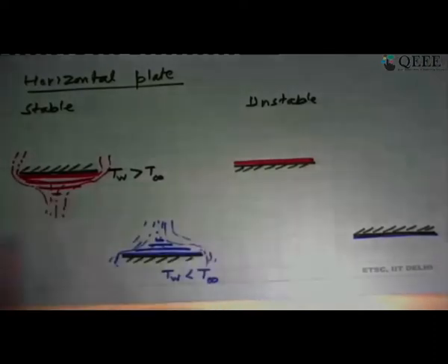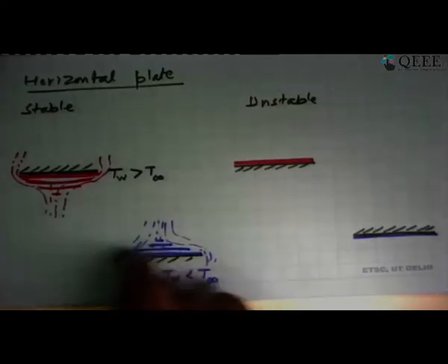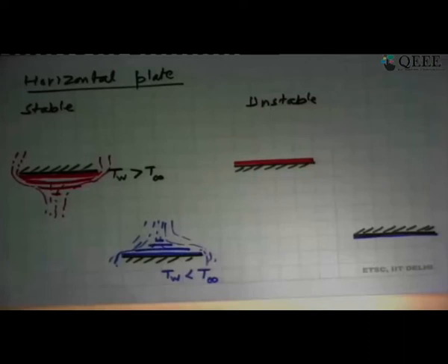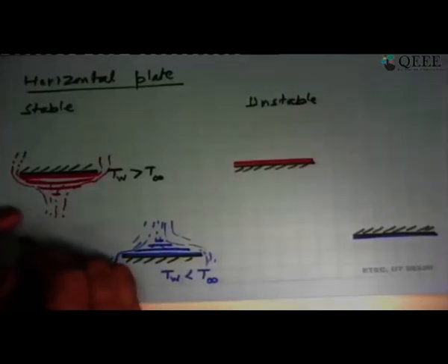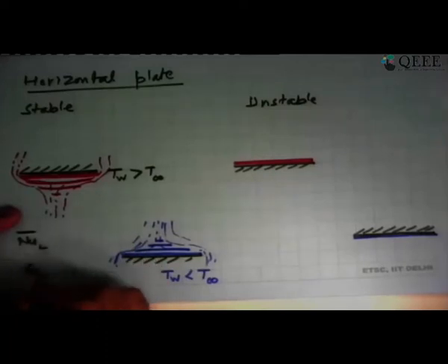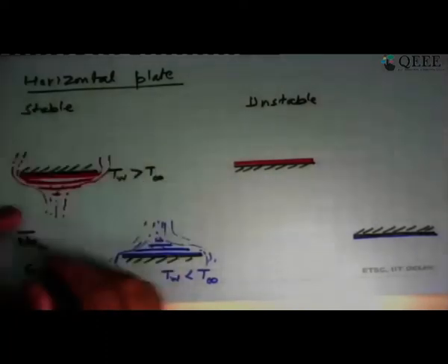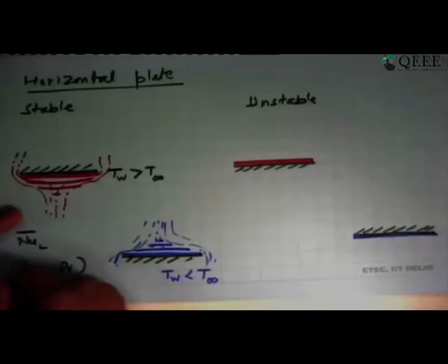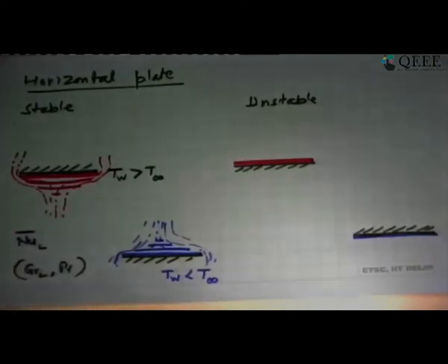And so you'll have, this is the coldest wall. The fluid temperature here will be slightly less cold, and finally it will be the ambient surrounding temperature. So that's the way the isotherms will get formed. So this is also a stable case, and for both these cases, we have reasonably nice correlations as a function of Grashof number, length, this parameter into Prandtl number, some function of this.